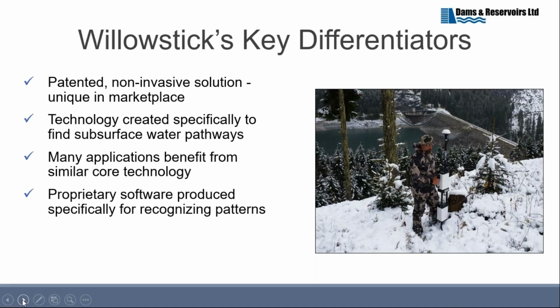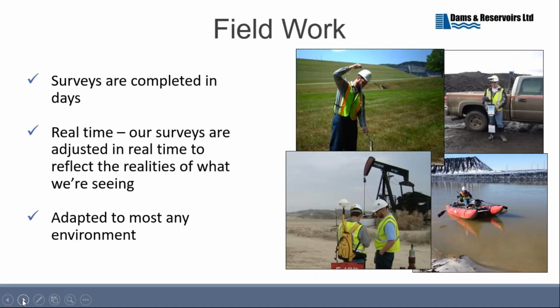And it's that instrument that we use across the site in question, and we take a magnetic field reading at usually 5-meter intervals across the site. We can vary that, and the spacing gives us better definition. The closer the points of survey, the better the definition of the survey. You can see here one guy using it up on the side of a reservoir.